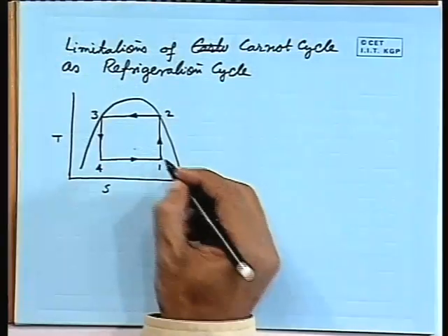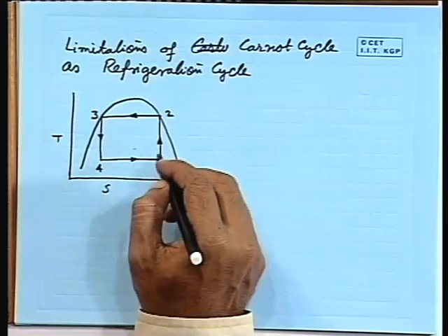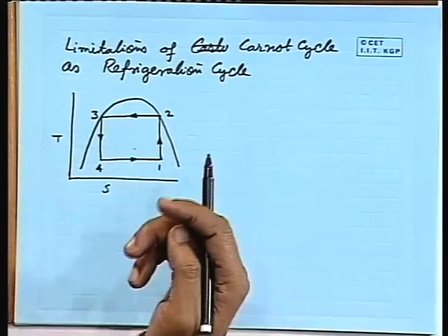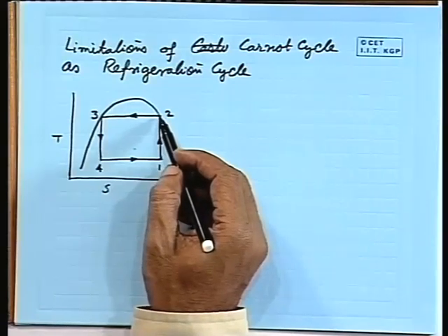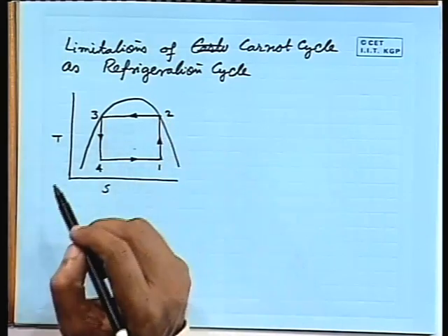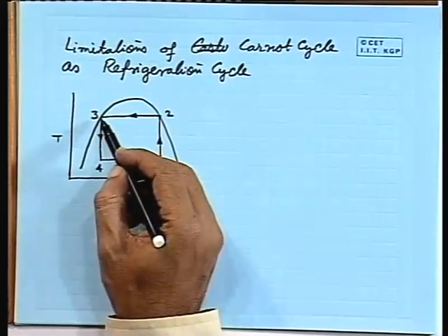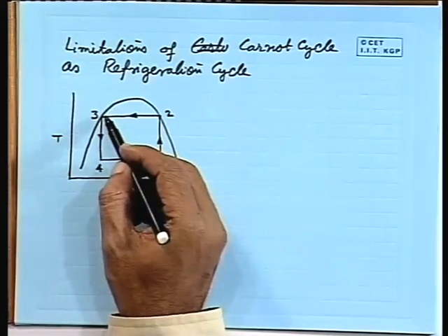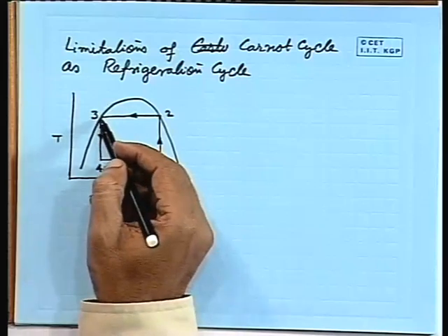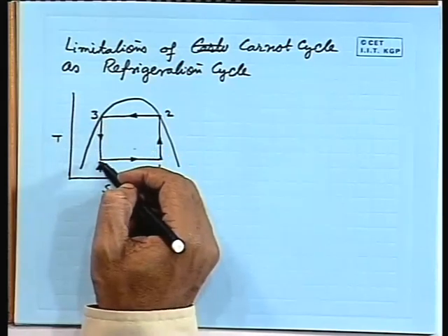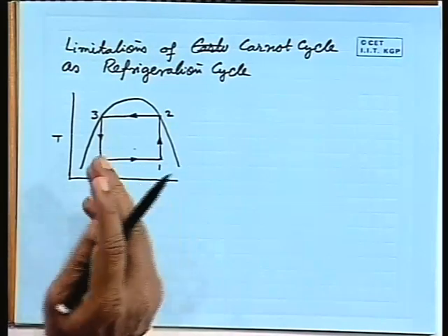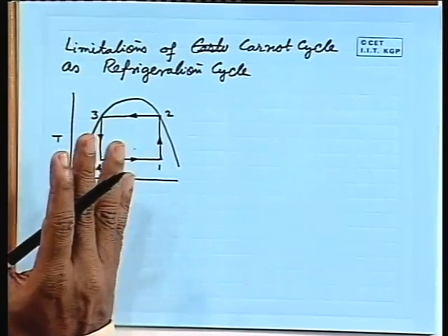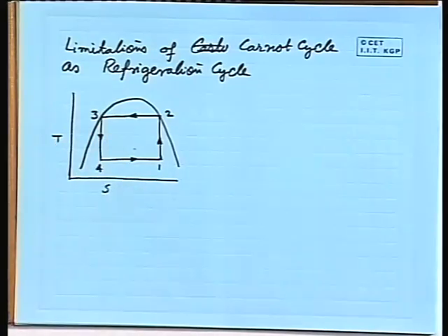All right. So, now here what we can see, we are compressing a mixture of liquid and vapor, and we are compressing it such that at the end of the compression we are getting saturated liquid only, and here we are starting from the saturated liquid, we are expanding so that we are getting a mixture of liquid and gas, at a fixed, given proportion.